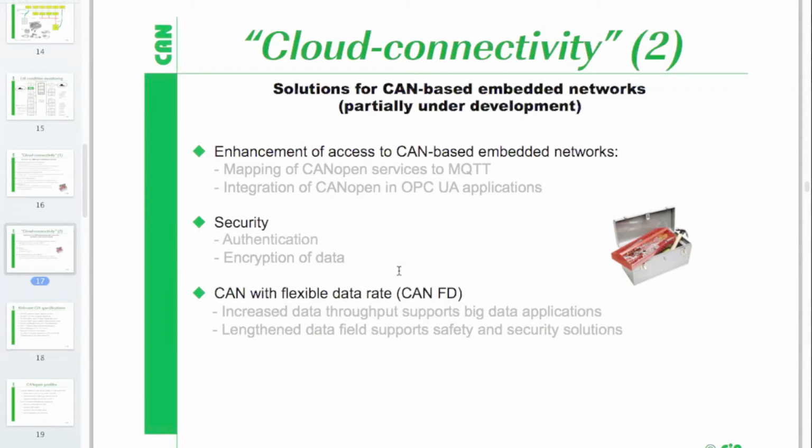We have a certain group, as I've shown you in the very beginning: the technical working group, safety and security. They are currently working on authentication and encryption of data coming through CAN and CAN FD based networks. We have had CAN FD technology for more than 3 years, and we have CANopen FD based on it, which provides certain interesting advantages, which we'll talk about a little later in this webinar.